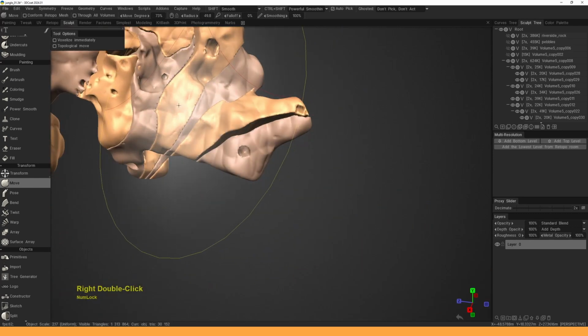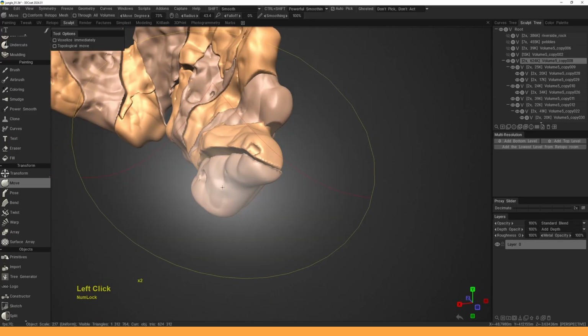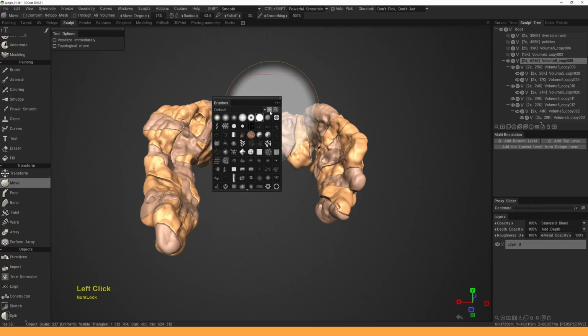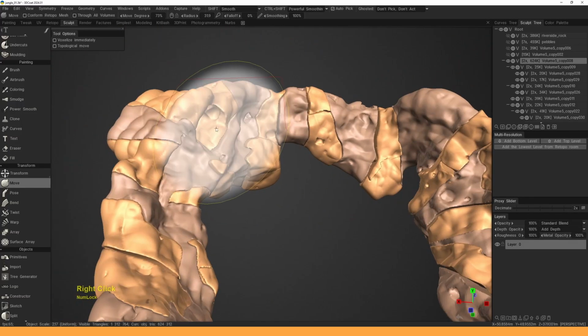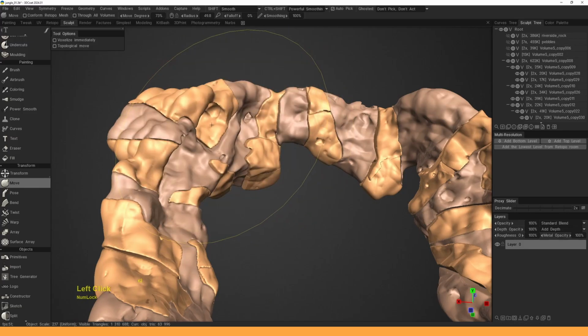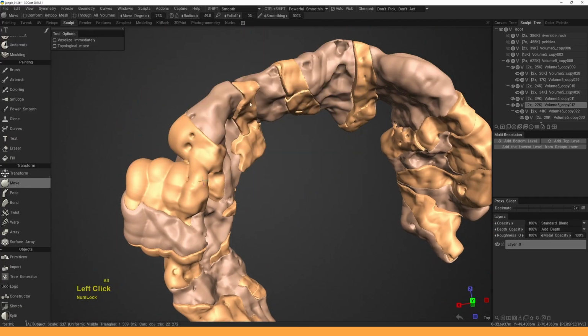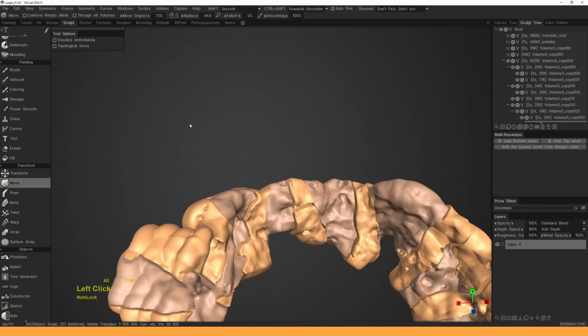Okay, maybe this. And actually, you can also choose a big bulky alpha, which will get rid of the soft selection and just push your complete volume as if it were a solid piece. So that's kind of a nice trick to know about.